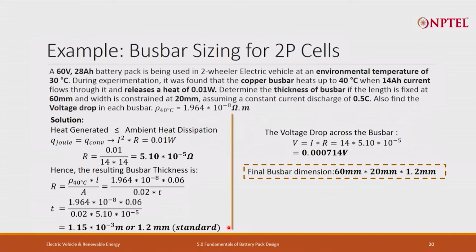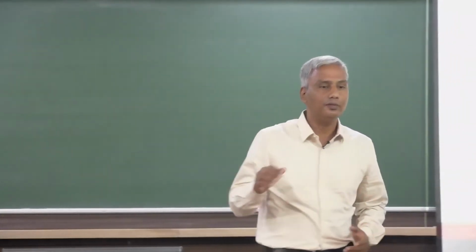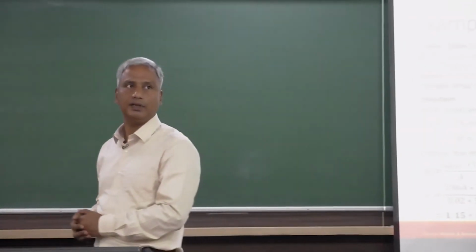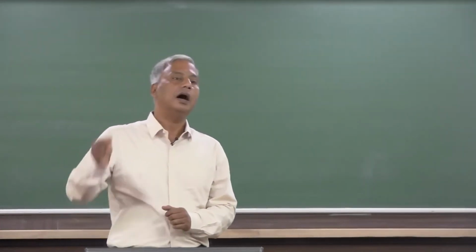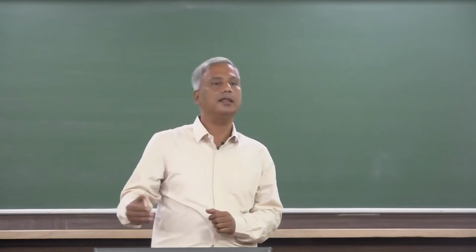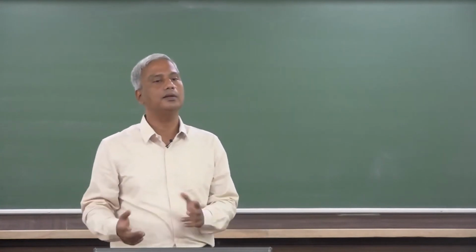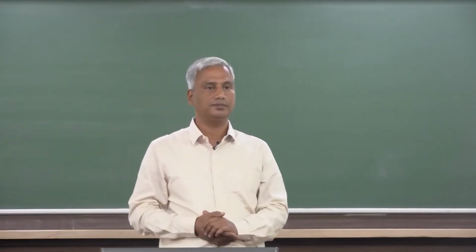Now it is easy because all the temperatures have been given, but let us suppose you do not have the temperature. Then you fix a design temperature, and then move on to an iterative solution, and then you find out the thickness which satisfies all other conditions. Okay.